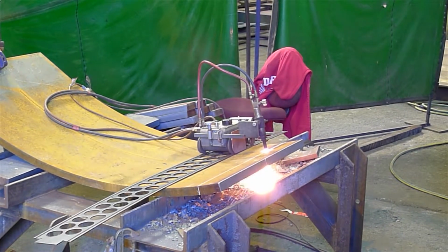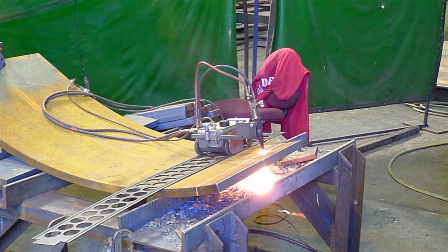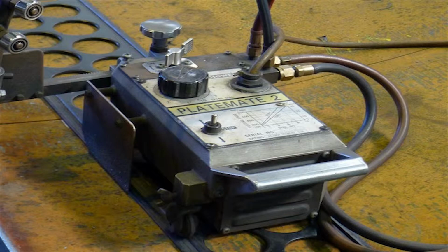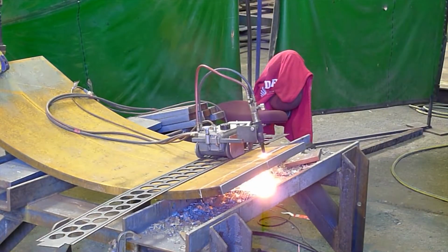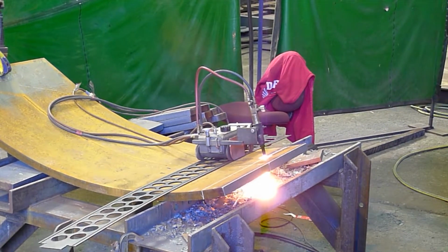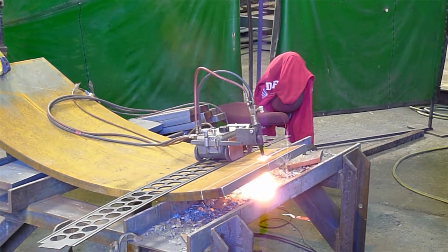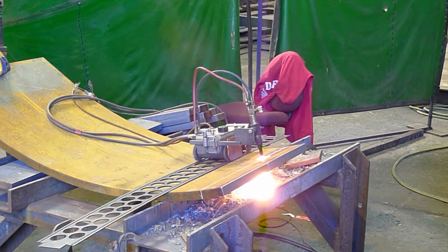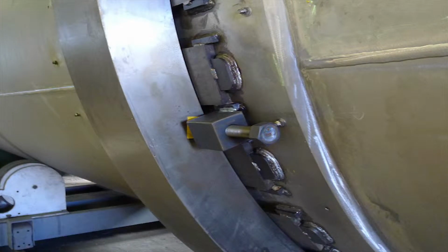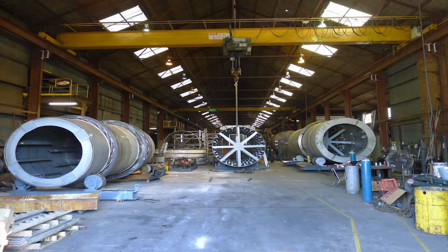Here we can see an example of oxyacetylene cutting. Because this is a straight cut, a guide is being used along with a plate mate, which is a mechanical feed unit produced by Sigwell. In this case, he is cutting a curved section of 50mm plate steel. It is curved to the outside dimensions of a drum roller being constructed. The cut sections are to be the teeth for a drive unit on the drum roller. You may be able to see the completed sections here attached to the outside of the drum. This 5-metre diameter drum is part of an ore drying mill being constructed for the mining industry.